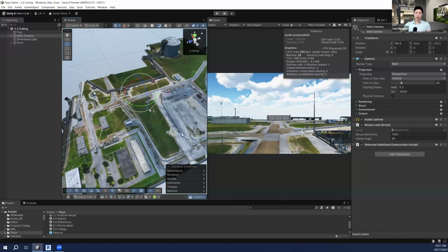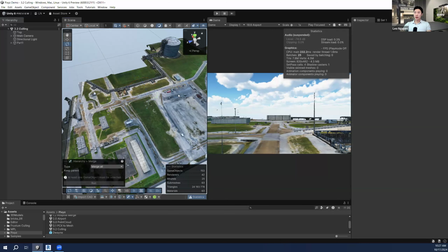And then Pixyz will also let you merge by region. So for example, if I open up the merge tab here, I can see that I could merge by regions, by hierarchy level, by name, or by material. So using a combination of the different merging tools that we give you, you could really optimize for the frustum culling system. So I'll go ahead and hit play here.